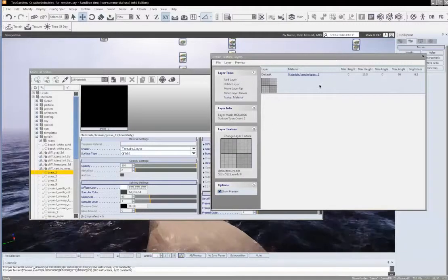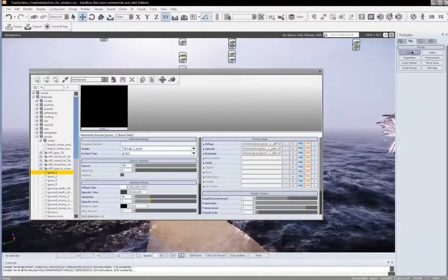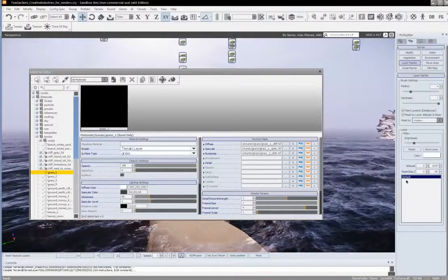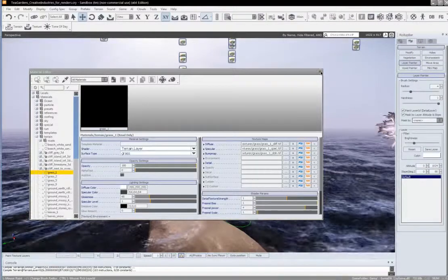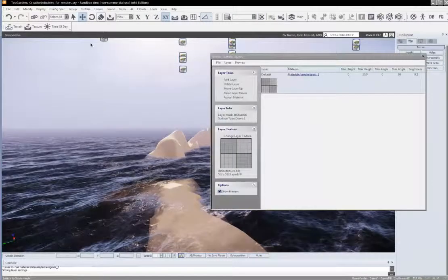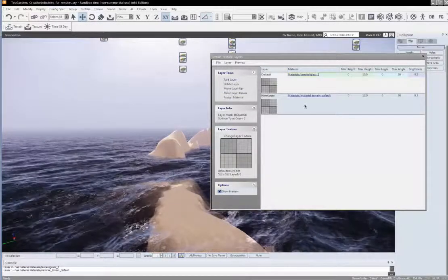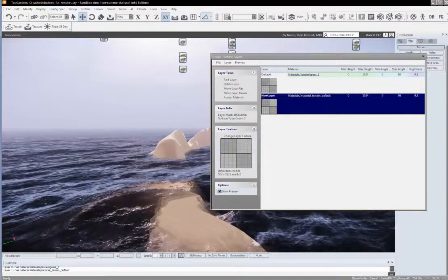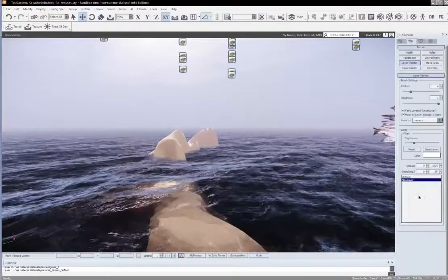And you can actually have multiple layers here. You can add more layers, and then I think it's over here in the terrain on the roll-up bar. You can go layer painter, and those different layers will be here, and you can apply different layers to different areas. For example, maybe I'll do that now. I'll just quickly add layer, and so this one's default, but it's actually called new layer, confusingly. I'll go to layer painter, and it should be here.